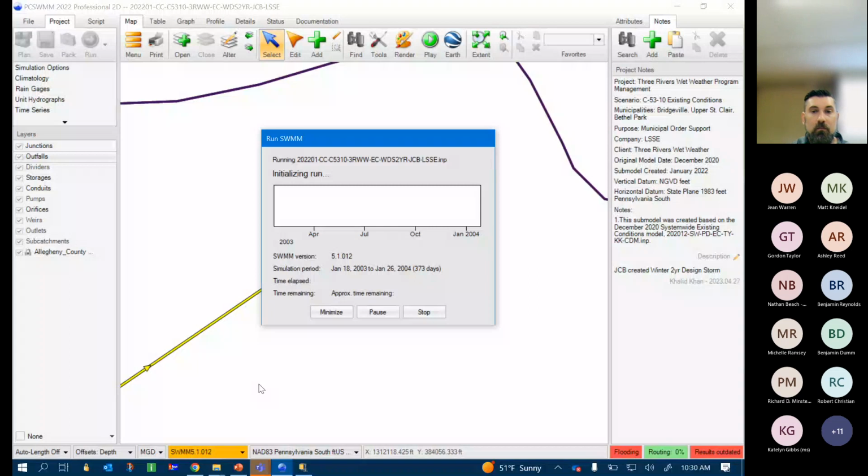As a reminder, what the hot start file does is wet the system. It represents flow occurring before your storm event to fill the pipes and let the system come to equilibrium before the wet weather events occur.